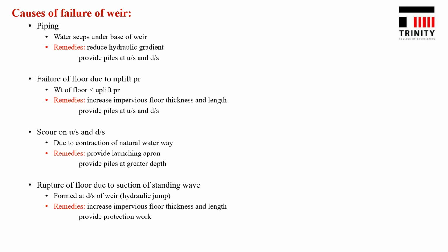The last failure is the rupture of floor due to suction of standing wave or hydraulic jump. It is formed at the downstream of the weir, which causes suction. It is a wave action, so that scouring of the body occurs. As a remedy, first of all we can provide sufficient thickness and length, then construct the wall with concrete instead of masonry. Since it is a concrete wall, the scouring rate due to the action of the wave can be reduced.